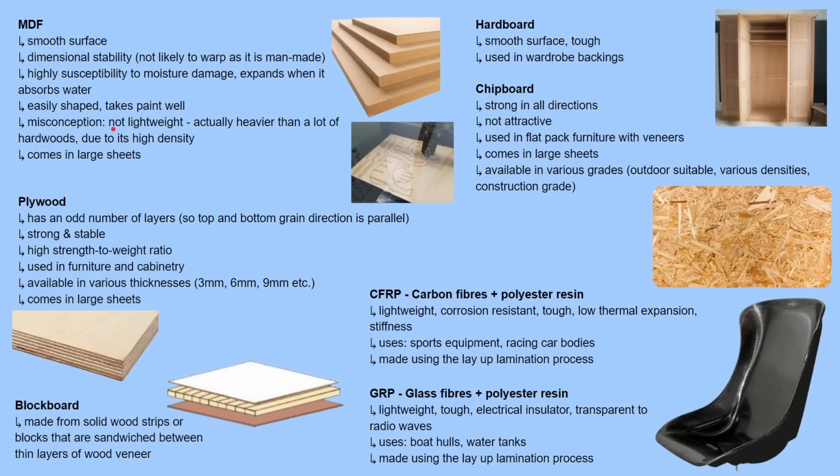A misconception is that it's lightweight. It's very common in the exam to say, oh, the material is lightweight. MDF actually is not lightweight. It's really dense. It's heavier than a lot of hardwoods as well. And it comes in large sheets, which most manufactured boards do. Normally comes in 1.2 meter by 2.4 meter sheets.